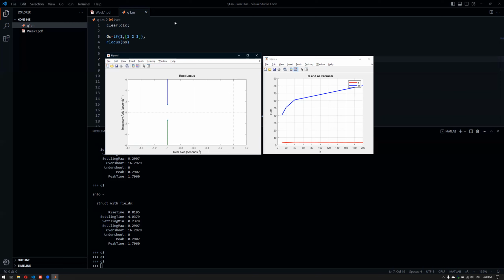Lower damping ratio means lower friction, therefore more oscillations and an increase of the overshoot value. So that's the things that I've used to conclude this. But there are many other examples that we can give here where we can try to guess how the system is going to behave.